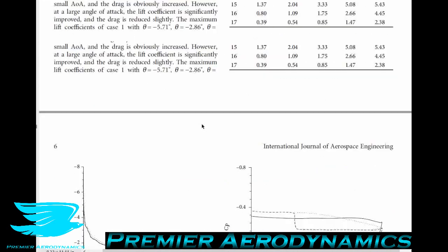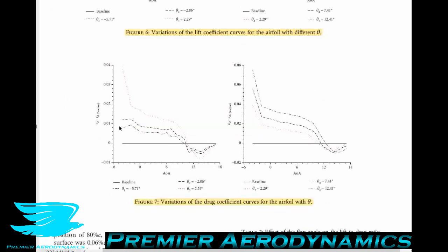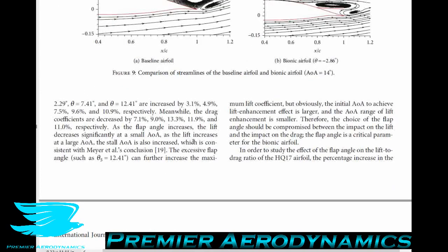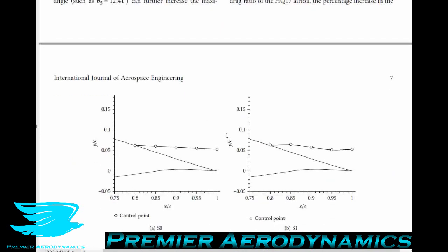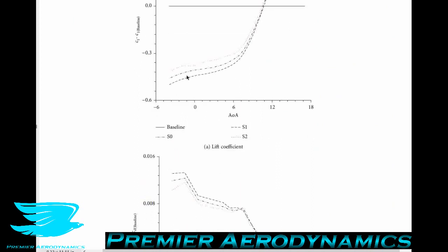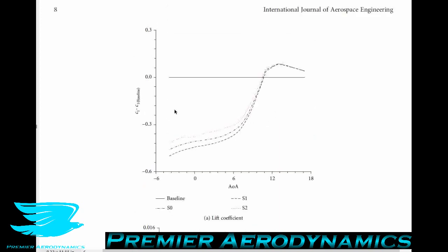So let's go back up to these figures here, where we have different angles of attack, and we can see that the more aggressive the angle of attack is, the more the reduction of the lift is in the pre-stall, but also the post-stall is more favorable. Curving the flap into an S shape, and not just being flat, has a slight effect in the pre-stall regime, and if the peak comes first, that effect is detrimental. So we can see here that this dashed black line, because we have the peak first, has a worse performance than any of the other flaps. If we have the trough coming first, that is then going to produce a better performing airfoil in the pre-stall regime and has almost no effect in the post-stall. So we're getting all the benefit with a reduced negative.